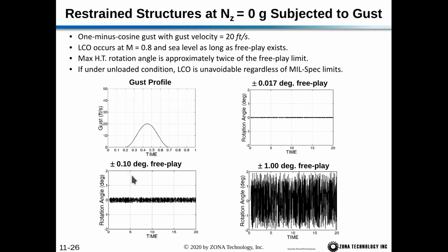When we reduce the Freeplay to plus or minus 0.1 degrees, our rotation angle is plus or minus 0.2 degrees. And when we reduce the Freeplay to plus or minus 0.017 degrees, which remember is the mil-spec, we still have a response of approximately plus or minus 0.034 degrees. So we still get the LCO because the horizontal tail is completely unloaded.